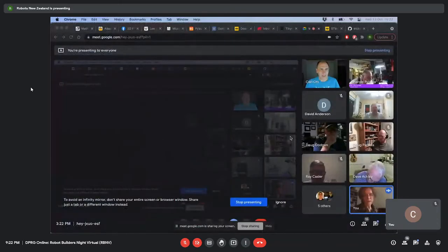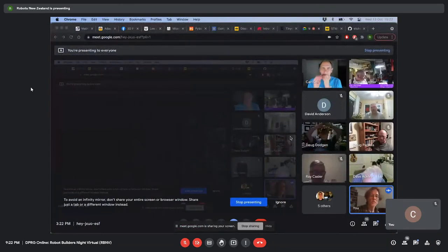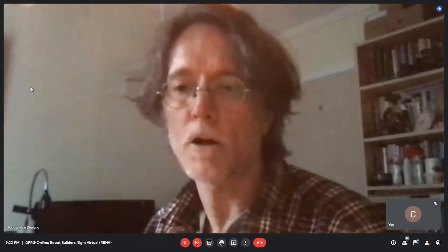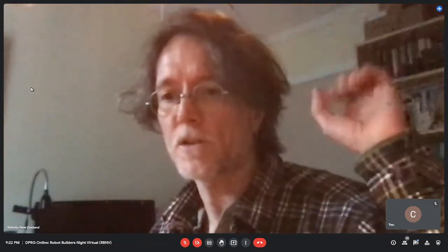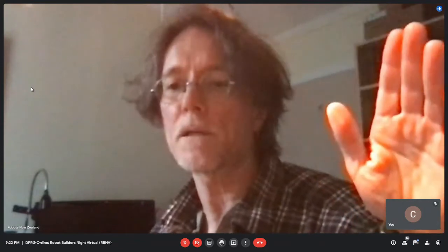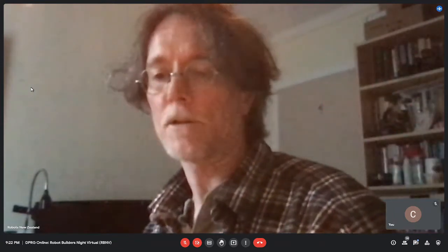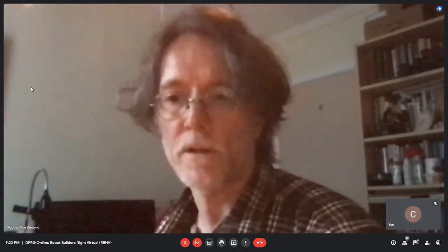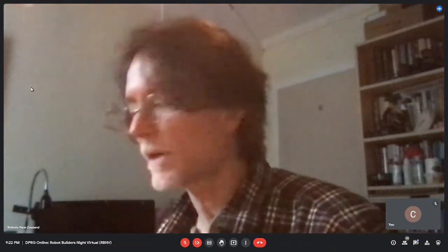What's happening basically is I've managed to get around having ballistic behaviors. These behaviors now get scheduled. Stop presenting, I think, is that right? Yep. What I've been trying to do is avoid ballistic behaviors. And what this is doing is scheduling, using what I'm calling a macro, some events into the robot's future that are just mixed in with the regular events, but can be canceled by a higher priority event. So if something higher priority like the back bumper comes through, it will cancel any macros that are running and take over the robot.